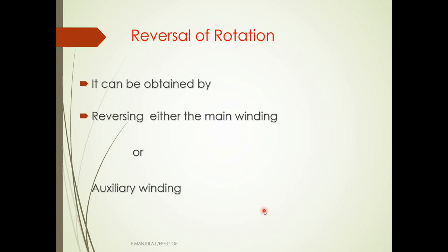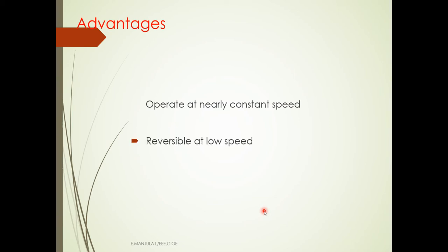Okay. The reversal of rotation. How is it possible? It can be obtained by reversing either the main winding terminals or the auxiliary winding terminals.